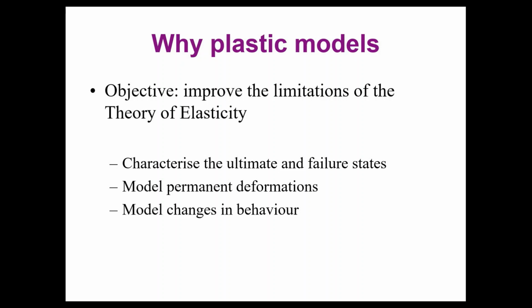And we need to model the changes in behavior, because our materials, for example steel or reinforced concrete, may start behaving as linear elastic at the beginning, but sooner or later, when we increase the value of the loads, we are going to change this behavior from linear elastic to plastic behavior, for example. That is the topic of this lesson.